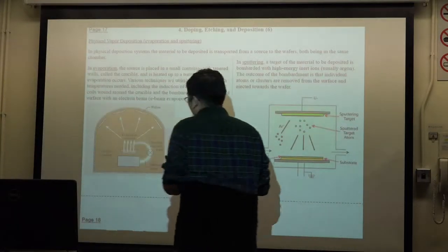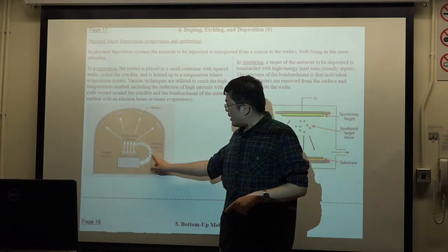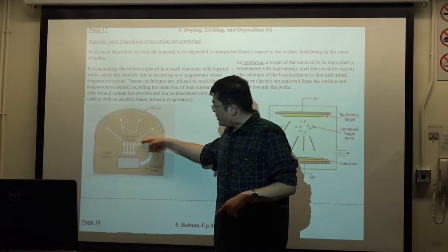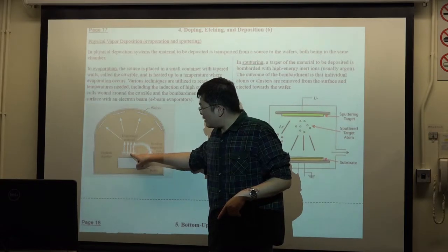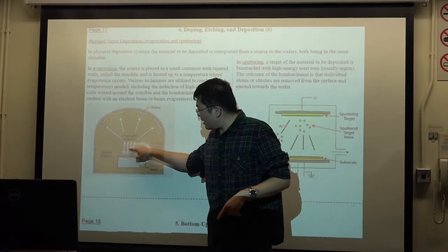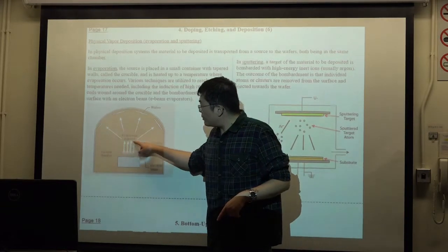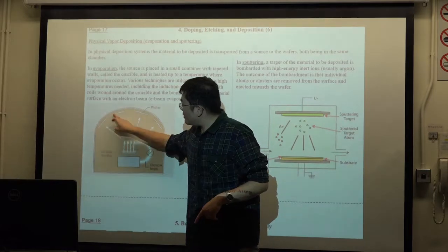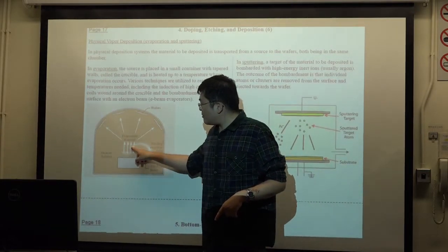Same chamber. You can see they use an E-beam. They have a magnetic field that can deflect the E-beam, and then inject it here. The E-beam collides and excites some evaporable material. This evaporable material evaporates onto the wafer, because this is the source.